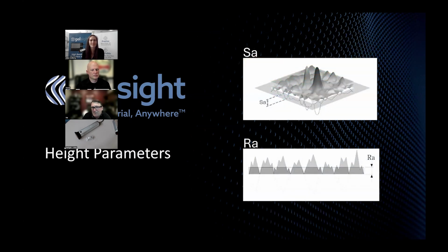Now, as I mentioned just now, the algorithm itself is almost identical, but the SA parameter is calculated over, in the case of GelSight Max, roughly 15 million data points. There's a lot of data. But modern computers can crunch that data very quickly and compute an average value. That average value is the absolute difference between each measured point and the plane that's been fit to the data.